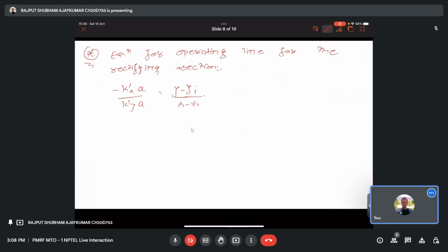What we'll do is try to see some of the concepts of how this exchange happens. The mass exchange between the vapor and the liquid phases in the distillation is mostly controlled by the vapor phase resistance. Thus, for the sake of accuracy, it is advised to calculate the packed height using the gas phase transfer coefficient. Following the procedure described earlier, it is possible to combine the heights of the individual transfer units to obtain the height of overall transfer units. We already have these equations: 1 upon capital K_y' equals 1 upon small k_y' plus m upon k_x'.